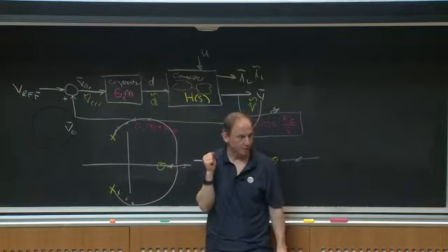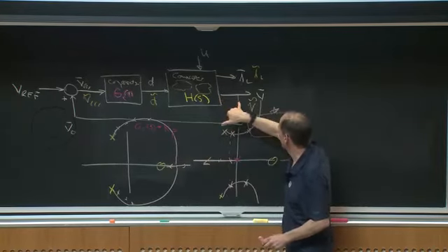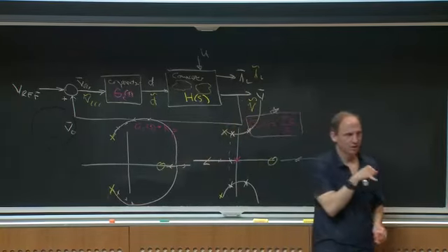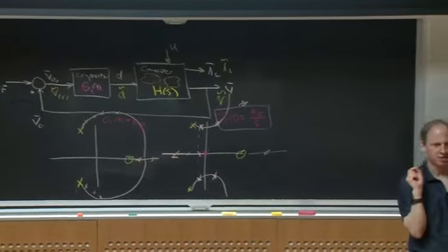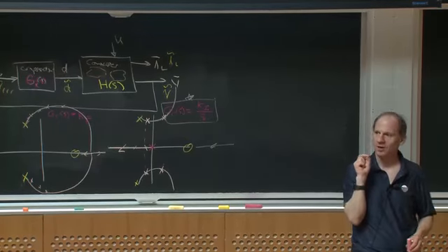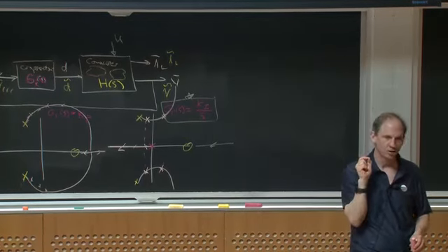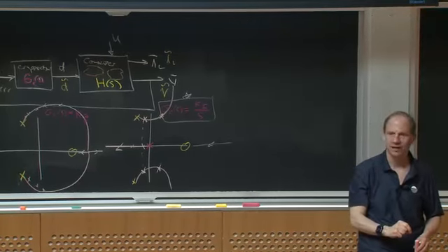And it turns out that just by doing better control, by looking at the inductor current and the voltage, I can make a better controller that will lead to a much more nicely damped response, okay? And we will talk about that, and that technique is called current mode control or current program control, and that will be the topic of next class.